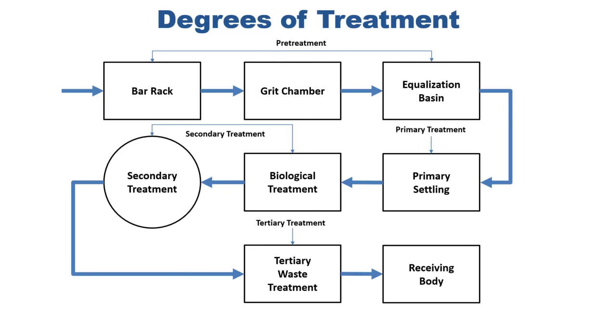Some of these processes can remove as much as 99% of the BOD5, phosphorus, suspended solids, and bacteria, and 95% of the nitrogen. They can produce a sparkling clean, colorless, odorless effluent. Although these processes and land treatment systems are often applied to secondary effluent for tertiary treatment, they have also been used in place of conventional secondary treatment processes.